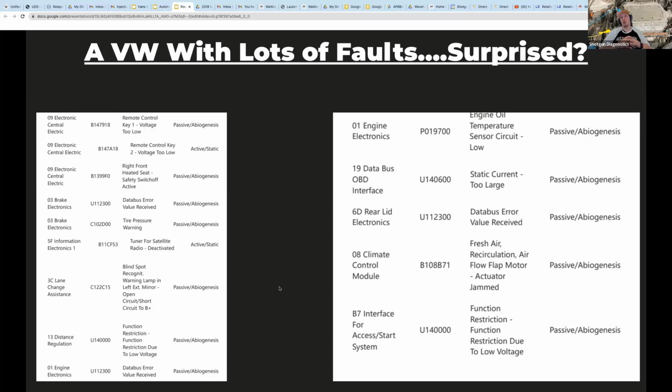So I said, let's get a charger on this car. And I don't mean a regular charger, I mean a power supply. There's two very distinct versions of battery chargers. There's regular battery chargers where they do variable voltage and steady current. That's a conventional battery charger. And then there's a power supply style charger, which is what you need to use for programming and diagnostics and ADAS calibrations, which holds a steady voltage and varies the current in order to maintain a steady voltage level.